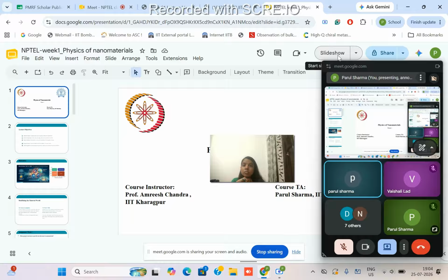It says it's a phenomenon where decreasing the grain size of polycrystalline material, it will increase its yield strength. So whenever the grain size will decrease to nanoscale, the number of grain boundaries increases. So when the grain boundaries will increase, it will block the dislocation motion. There are many grain boundaries, and now the motion is prohibited, so it will automatically strengthen the material.